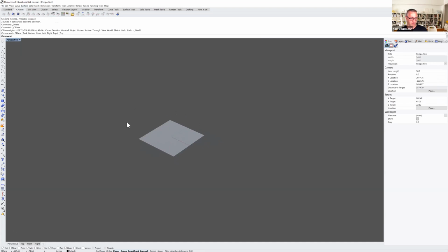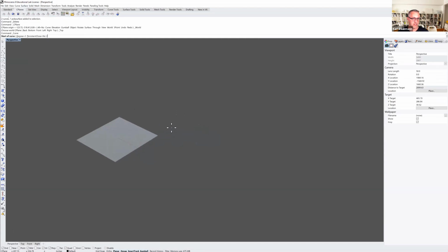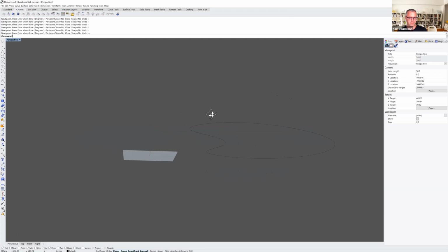And so what patch will do is if we draw, I'll draw alongside the construction plane, make a kind of perimeter for something. So we could make a flat surface using a planar curve, but what we can do is maybe either use curves or points.